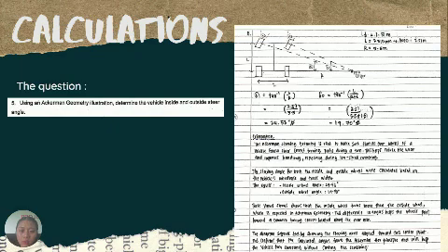and we got the value t equal to 1.51 meter, L, which is the wheelbase, is equal to 2510 millimeter, and I convert it to meter and get the value 2.51 meter, and R equal to 5.6 meter. After that, we use the formula to find the outside and inside steer angle by using the formula